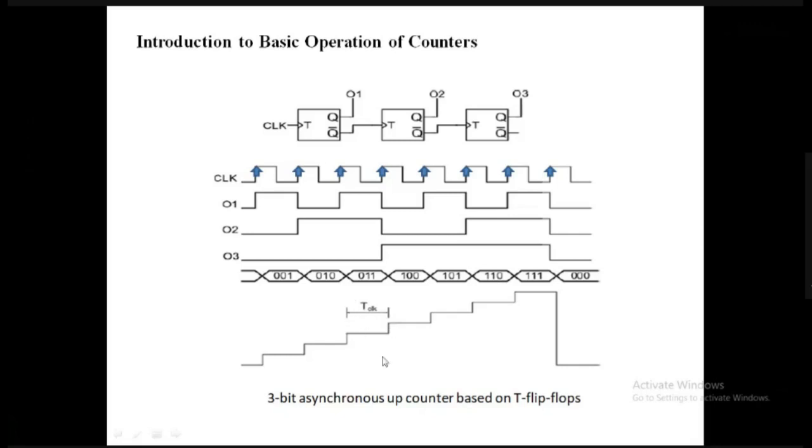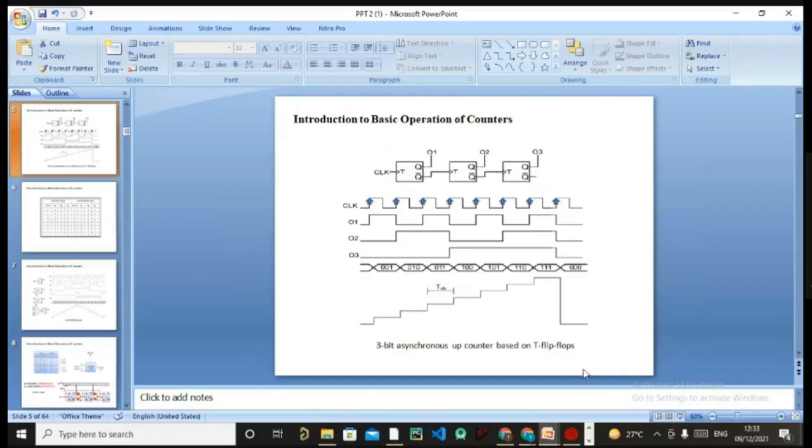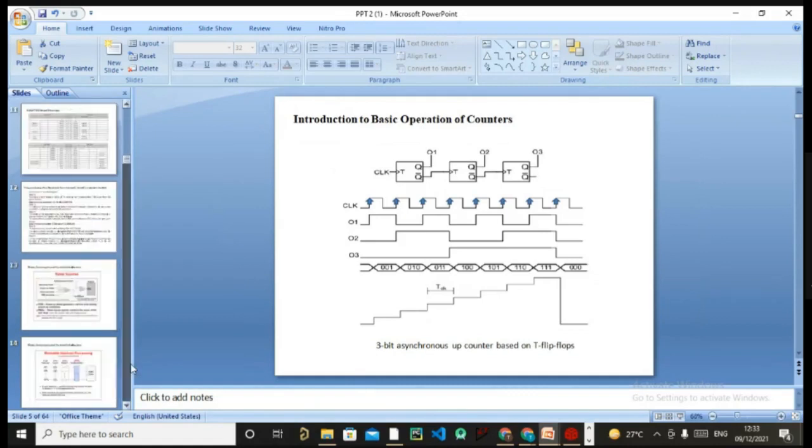So I'm saying if my clock is operating, because this is what my time-base submodule is doing, right? My time-base submodule has a time-base counter which is running from 0 to a certain value. The timing for that counter will be T_TBCLK. Am I correct? So the time for a counter to rise from one step to another will be 1 divided by the frequency of that time-base counter which I am operating, right? Is it clear to you all?